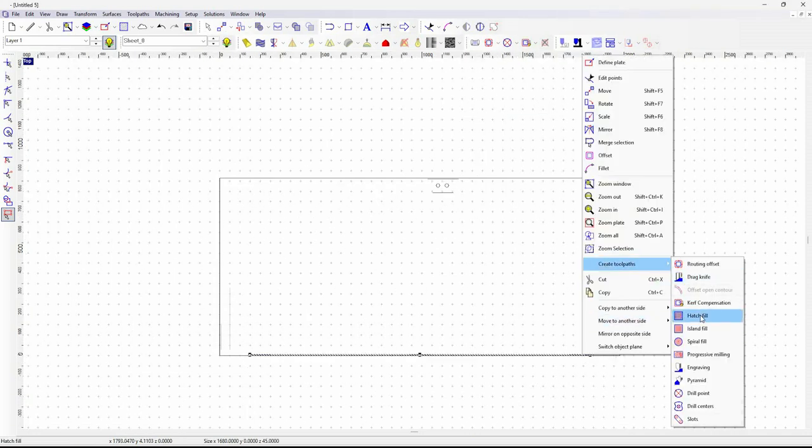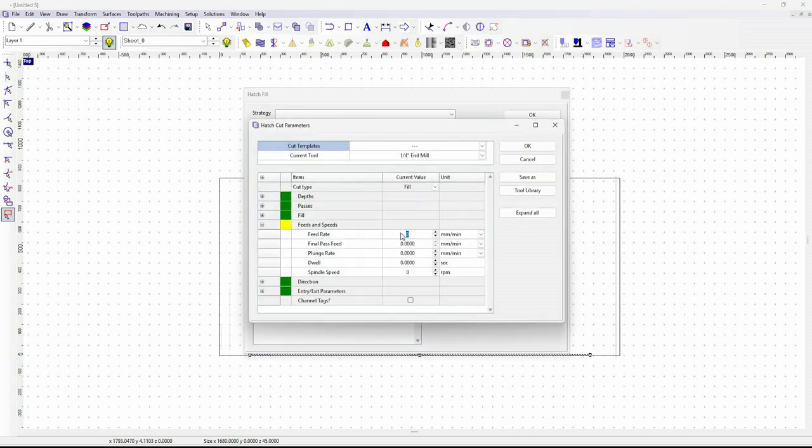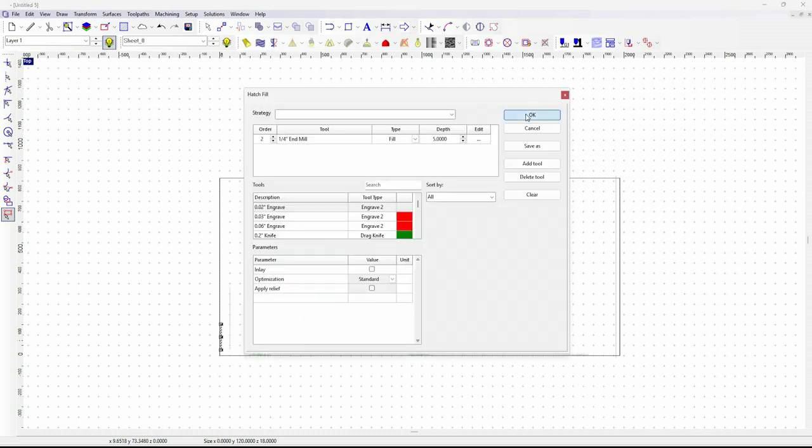For demonstration purposes, we will use the same tool on all sides and apply it with pocketing strategies. To pre-drill the screw holes for the lock mechanism, we will use the drill center strategy, and these will be cut with the horizontal drills of this machine.